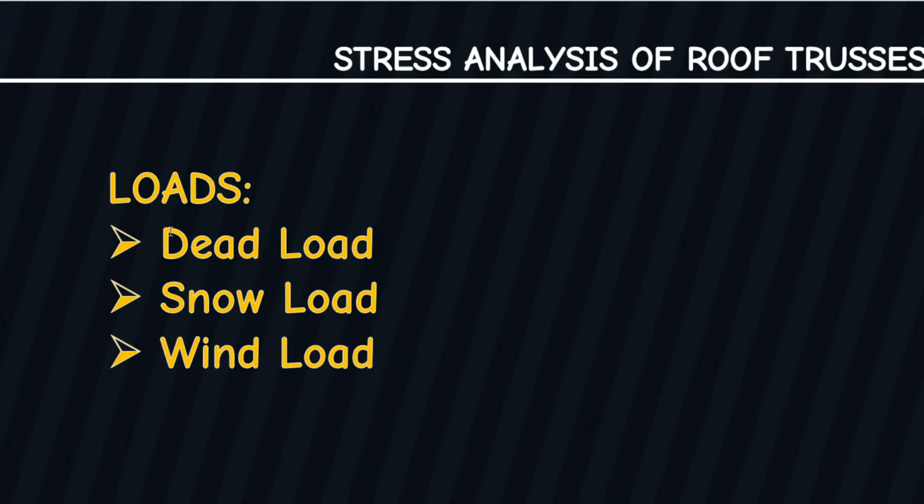So what are these? The composition of dead loads. Just listen. The dead load includes the weight of roof covering. So our sheets, that is already a dead load. All the materials in our truss, everything the truss carries, that is a dead load. Okay?